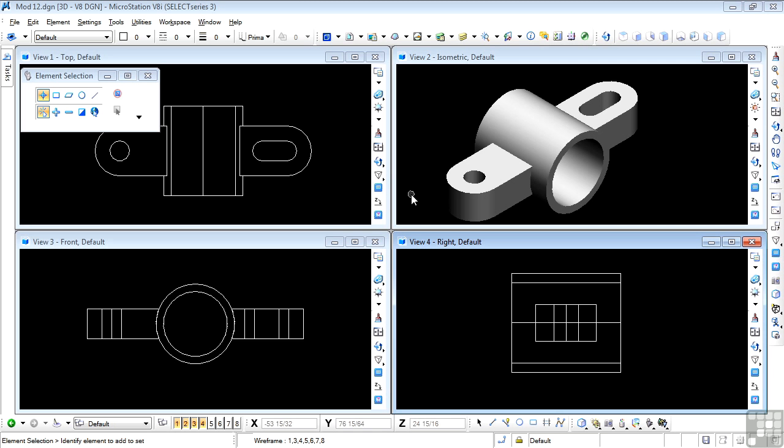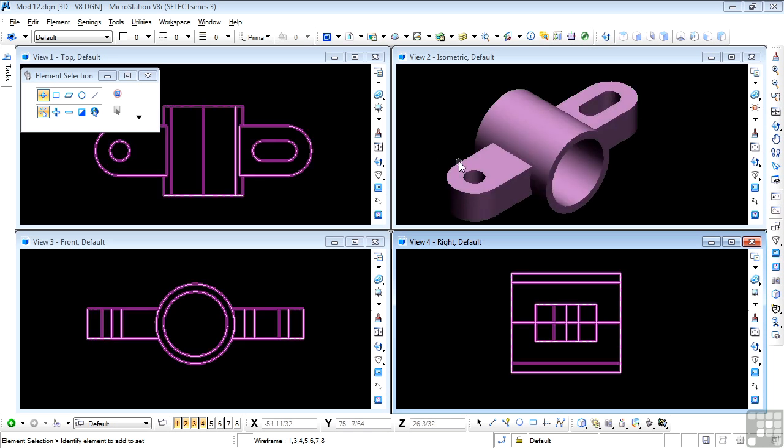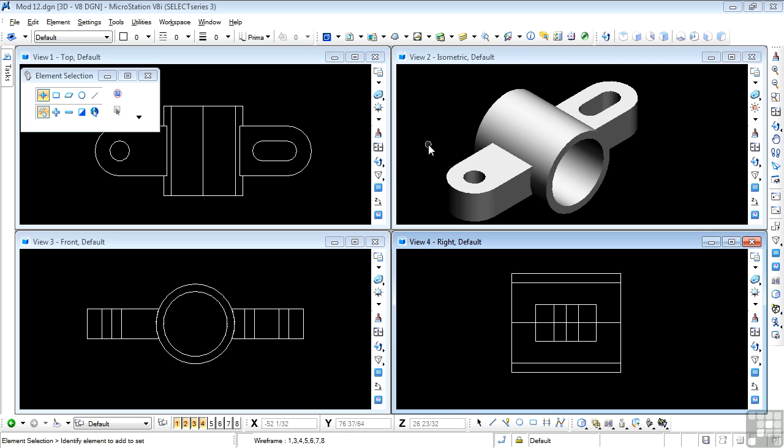Having made the design file, you might want to make a couple of copies of this base design file, which you can use later on when we get to the other presentation methods and tools. And one thing you do need to do is make sure that the bushing is a solid single object. If yours is still in the 3 parts that we previously made it from, then you need to go to the Unite Solids tool on the Modify Solids toolbox and use the Create a Union to create the single solid